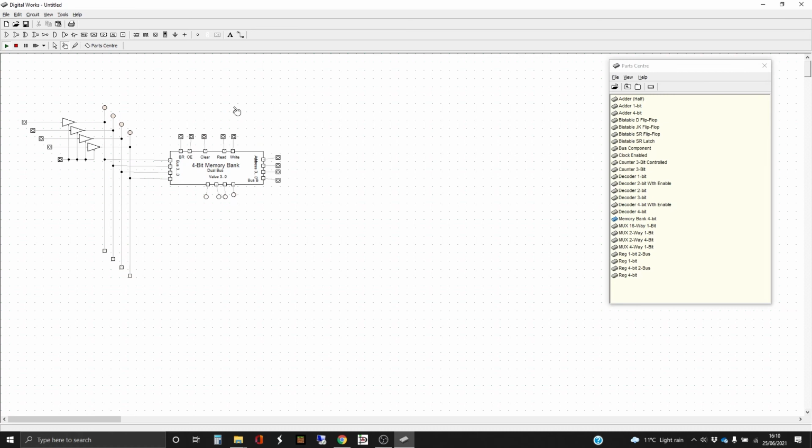It's kind of hard for us to know because the only way we can find out what's going on in the memory bank is by sticking an address and doing a read. So, well, in fact, let's use address 0000, and we're going to read from there, and whatever's in there should appear now in our value. But it's 0. And that's how it should be because we've just cleared.